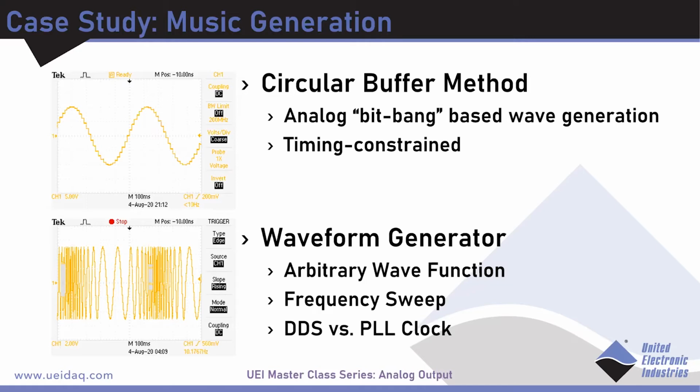The image I have on the top left is a wave that I generated using the AO308. I picked 20 points along a sine wave, right, and just had the AO output them consecutively using a certain timing scheme. And as you can see, it's good.